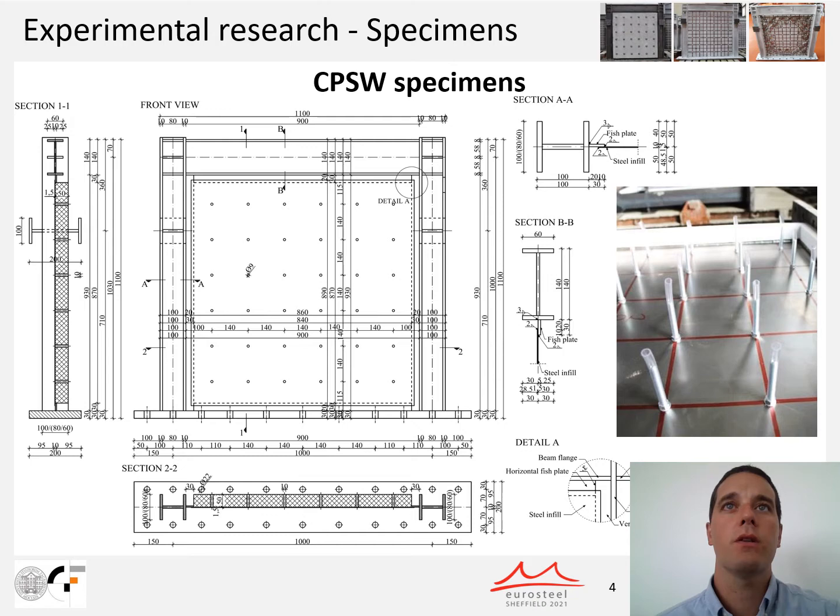Additionally, direct contact of the reinforced concrete panel with the boundary element was also prevented, leaving a 30 mm gap around the reinforced concrete panel perimeter, which in previous research has been shown to enhance composite plate shear wall behavior, but is also necessary if prefabricated reinforced concrete panels are being used.